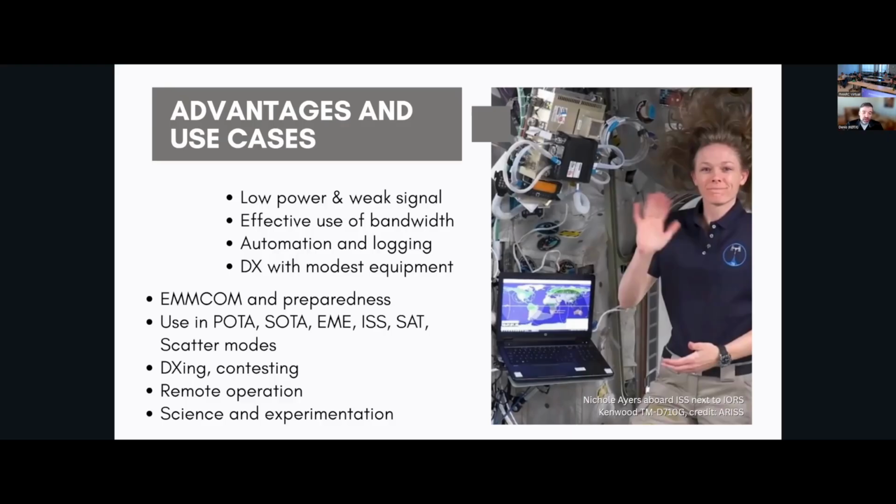For example, you can see if your antenna works, if your system works by utilizing services like PSK Reporter. It's a website where it will show you on the map who can hear your signal. So you can call on FT8 or WSPR, and that will show the propagation of your signal. You can troubleshoot your system with the digital modes, and you can experiment with antennas and see how it works. So that's very useful there.